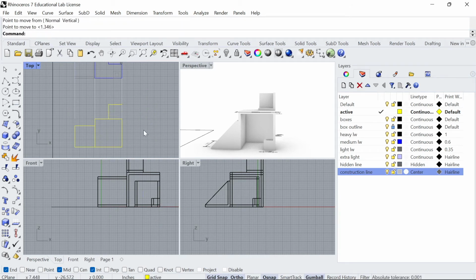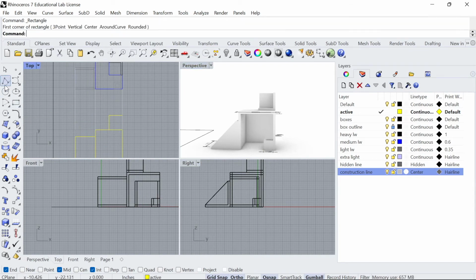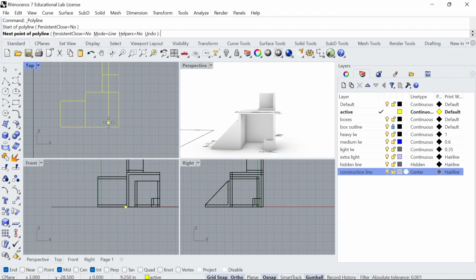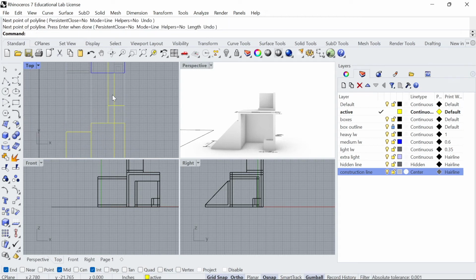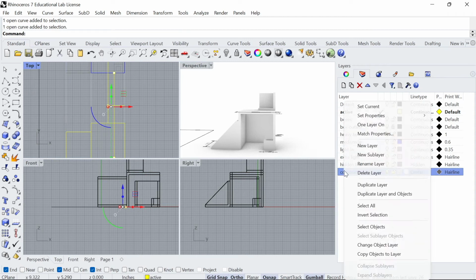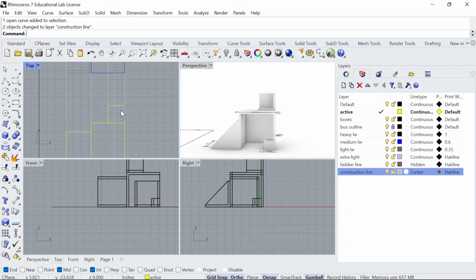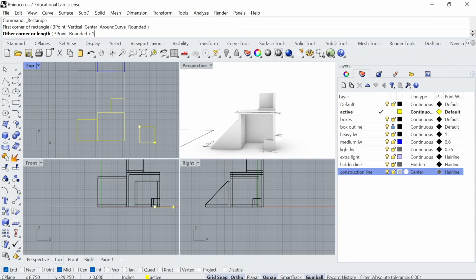And then we got the one inside. You can see it's right here. And if I created my construction line, you'll see this one matches right there, which means, I'll just draw it anyway, which means that this 1-inch box is going to come somewhere down to this point, right? So if I move these to construction lines, you'll see that the 1-inch box is going to land somewhere here. The height of it in the side view is not determined yet. I need to draw the 1-inch box or square to understand it.